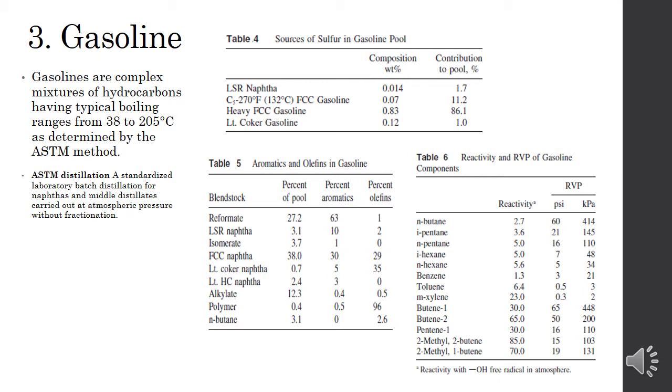For maximum octane with no lead addition, some refiners have installed isomerization units to process the LSR fraction and achieve PON octane improvements of 13 to 20 octane numbers over that of the LSR. Catalytic reformate is the C5 plus gasoline product of the catalytic reformer.